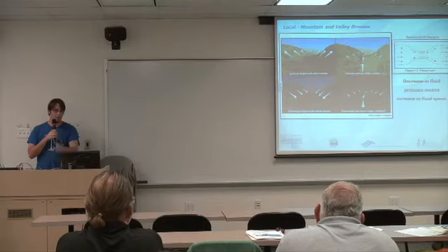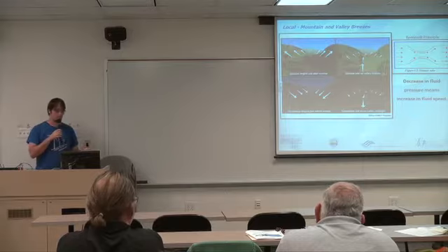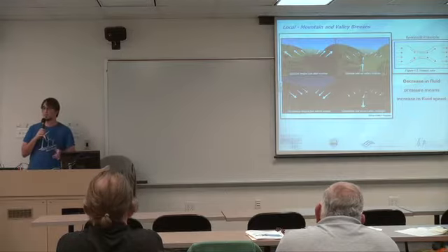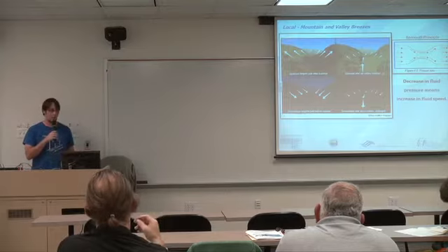You know, in order for the flow of the wind to maintain a certain energy, as the pressure decreases as it goes through the confined space of the valley, the speed increases. And as I'll show you in a moment, the speed of the wind is pretty much the most important factor when it comes to determining how much power we're going to get out of it.